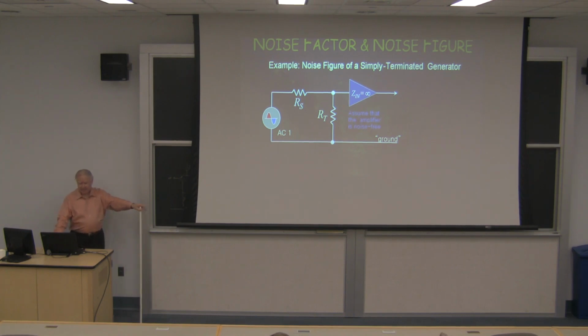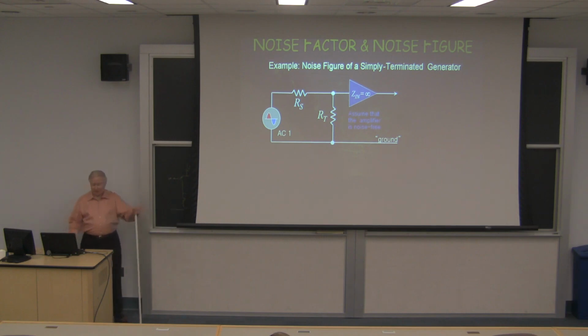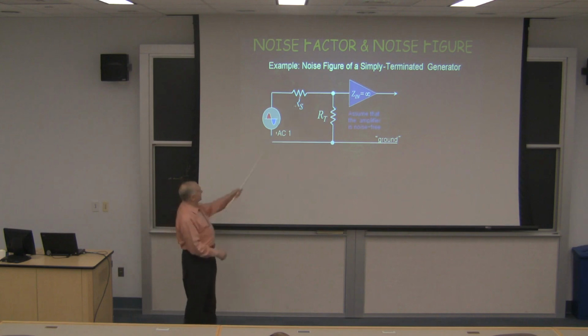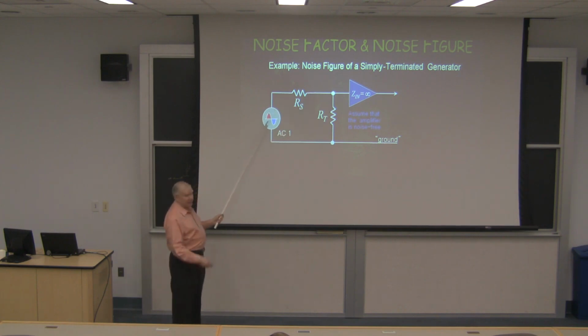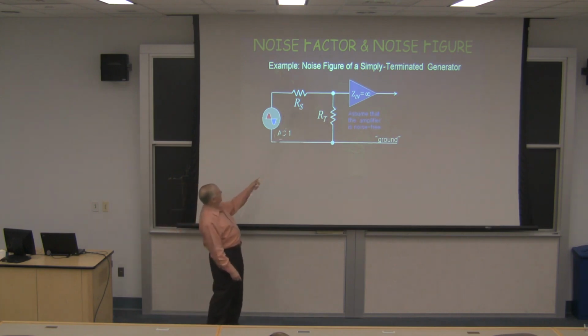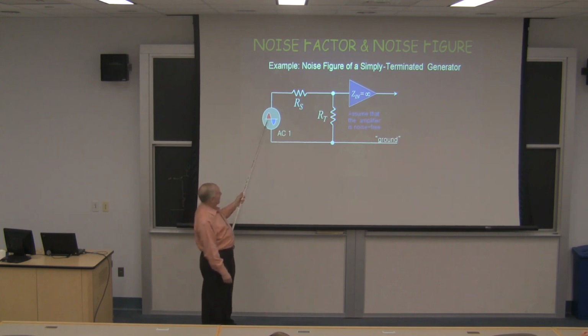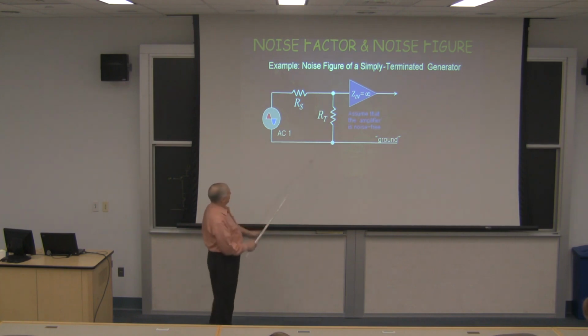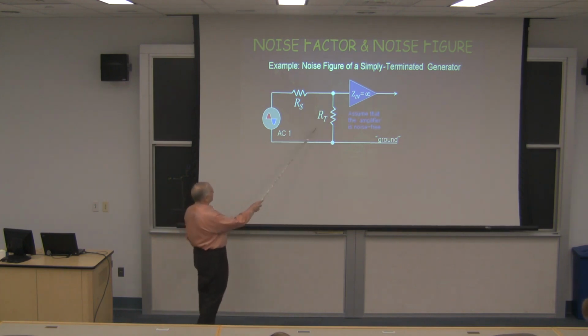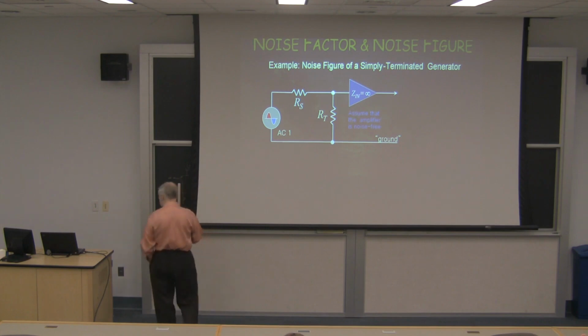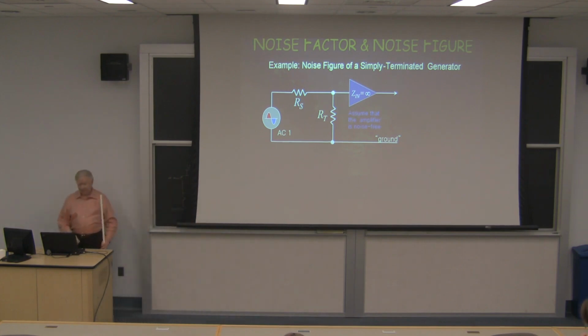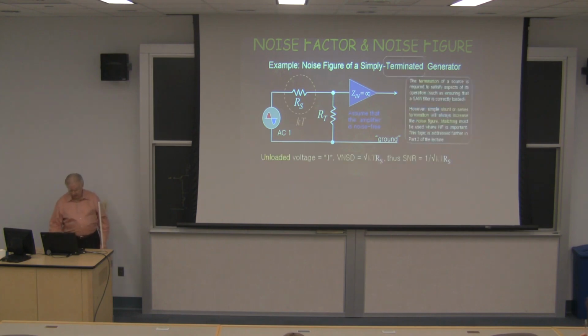So I want to give a quick example here before we start talking about noise sources of the important difference of termination and matching. Supposing we have a source resistance of Rs, and because it's connected to our system, say via a cable, or because the generator, in order to be calibrated correctly, or in order to operate correctly, as a filter, for example, needs to see the proper termination resistance from its own selfish point of view. But if we apply the termination resistor in this fashion, and we can assume for the moment the amplifier is just noise-free because it's a resistor we're worried about, you can see that you've divided the signal by 2. Let's have some equations here.